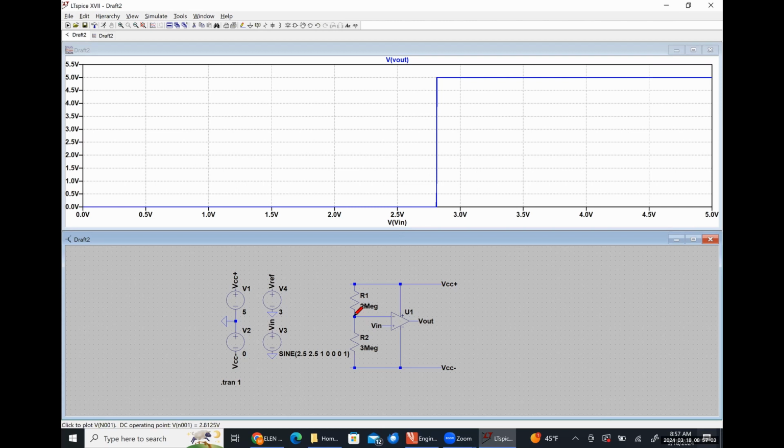This is because now our op amp is pulling a significant amount of current, because when the current flows through here, it sees a megaohm sized resistance down this path and a megaohm sized resistance down this path. So we're not limiting the current that's flowing into the op amp in this particular way, right? So that's why choosing the right size of resistor values is so incredibly important when biasing op amp circuits.